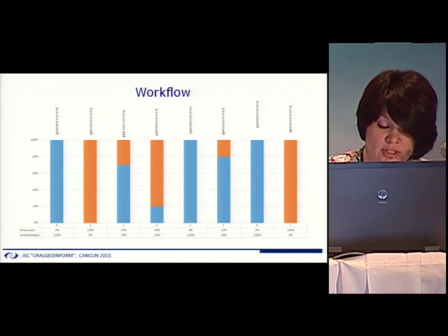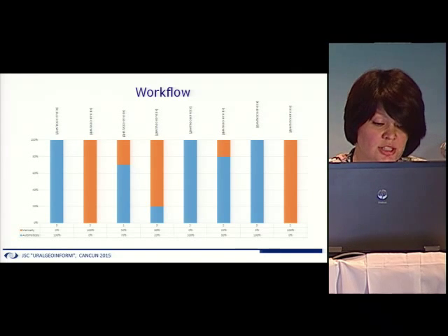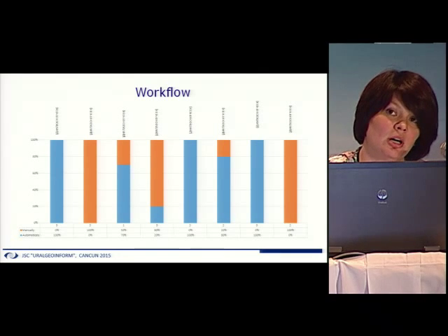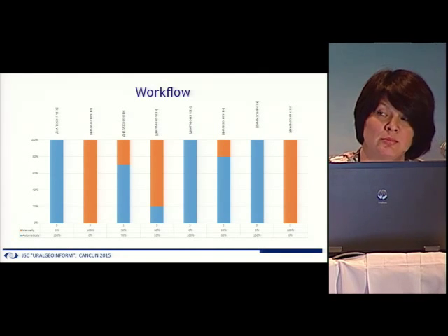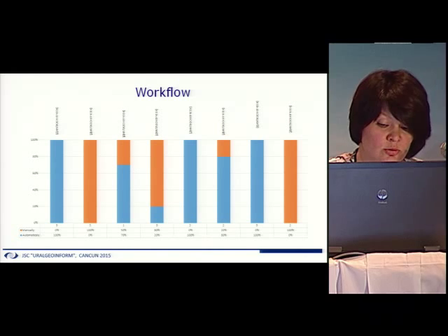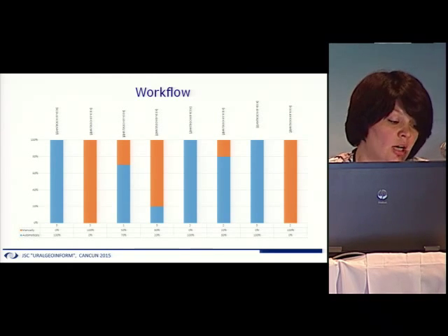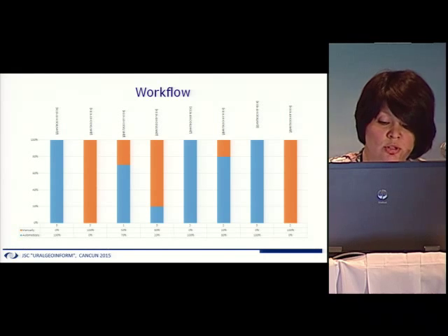We do it manually because images came in batches, and there were images that had no overlap at all. We called them holes. Some of the images didn't have overlap at all. So there were blocks of images that could not be connected to each other. So we divided the volume of work by 14 blocks, and adjustment and matching was done in parallel.